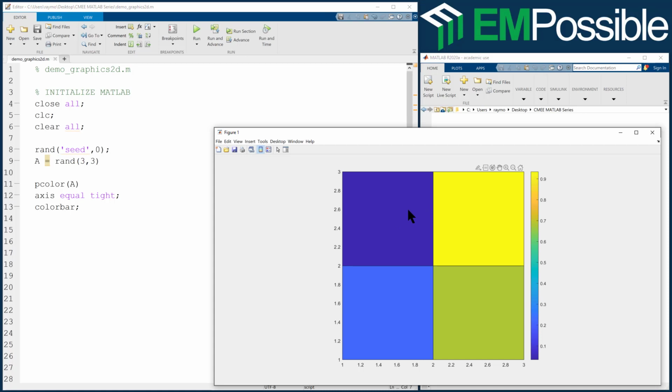So Pcolor does a very good way of smoothing and interpolating the data. So if I'm plotting smooth functions and I'm generating that very last figure that's going to go in a publication, I'll use Pcolor. For everything else, I'm using imagesc. So a 3x3 array of colors, I know I have a 3x3 array of pixels, and I can zoom into any one and figure out exactly what that value is at that array position.